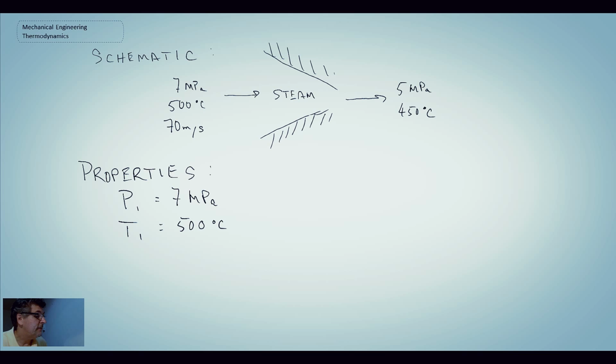And what you'll find, we're dealing with superheat, or with water, sorry. So what I would do, go directly to the 7 MPa table, and you'll see it's 7 megapascals. The saturation temperature is in brackets at 285.83 degrees C. We're at 500, so that means we're well above it. We're up in the superheated region.